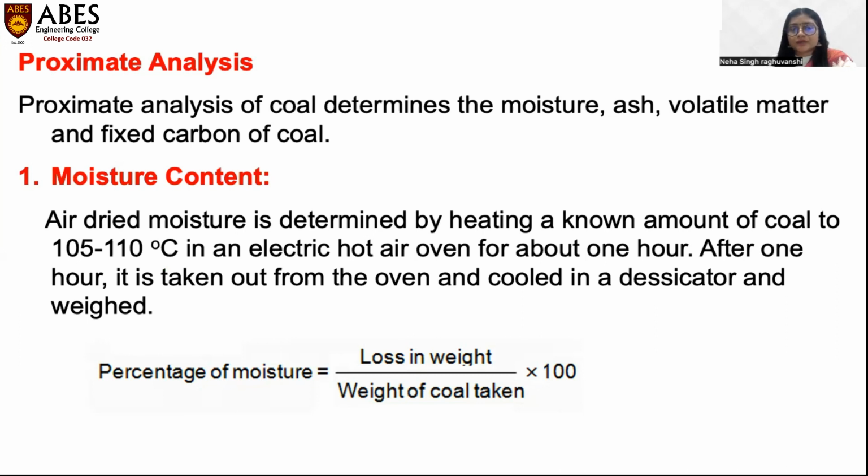Let's start with the moisture content. It's important to determine the moisture present in the coal because water does not support combustion. So if the coal has a high amount of moisture, it will not burn properly and it will not give a good amount of calorific value.